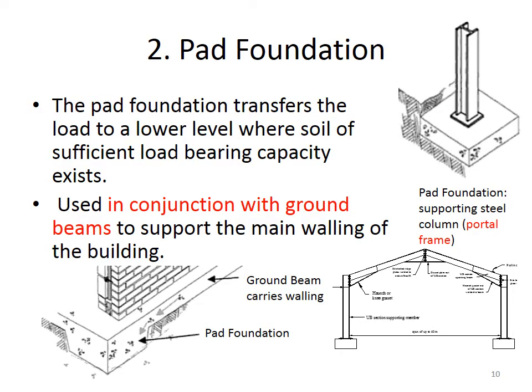Number 2 then, the pad foundation. The pad foundation transfers the load to a lower level where soil of sufficient load bearing capacity exists. So sometimes this is used because it's a portal frame construction. Sometimes it's used in order to dig down deeper than if we were going to use a strip foundation.